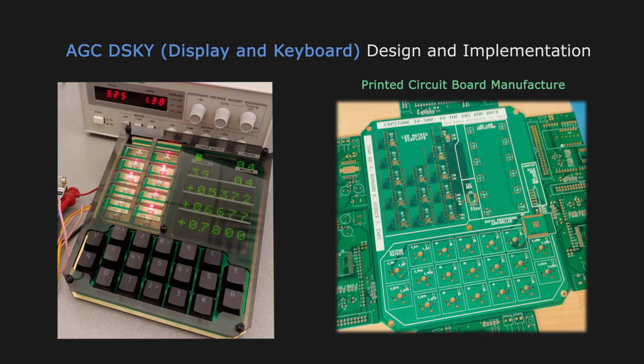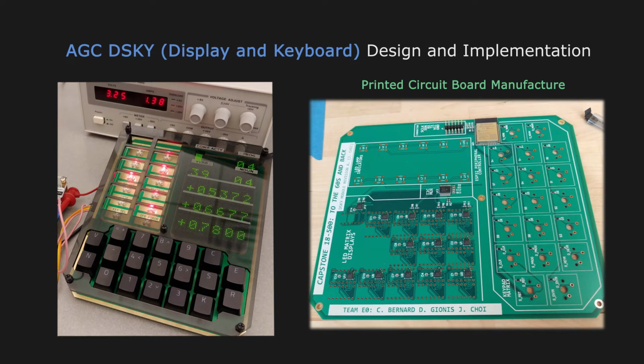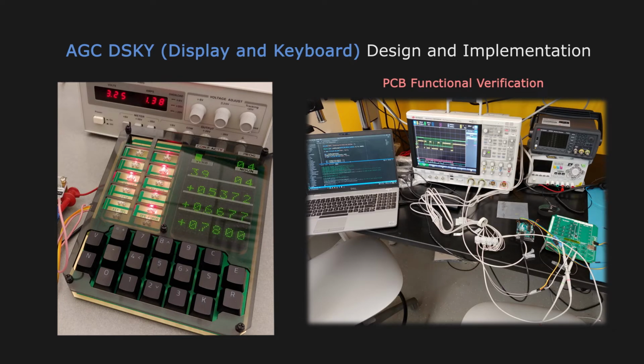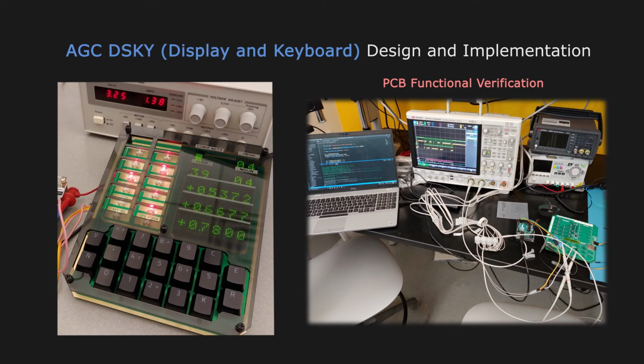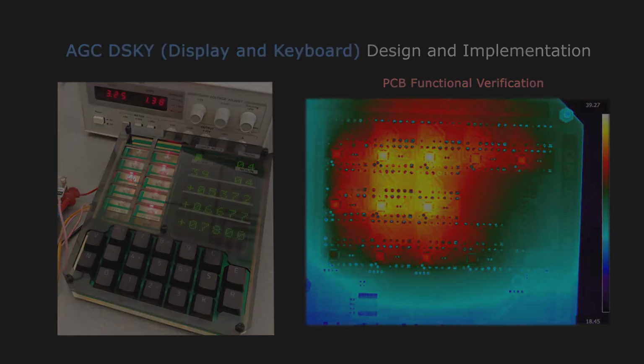After the PCB and the components orders were received, the board was manufactured in-house. First, the solder paste was applied using a stencil. The components were then placed carefully by hand on the board, and finally all soldered by baking the parts in a reflow oven, with the rest of the parts being hand soldered. The finished unit was functionally inspected and thermally profiled, all meeting the specifications, both for UART and I2C protocols and the temperature, with the maximum temperature being around 40 degrees Celsius.